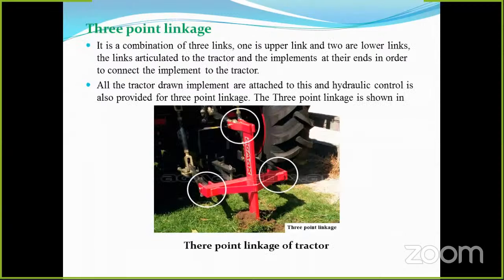Next, the 3-point hitch linkage system. See here, these two are lower links and this is the top link. By utilizing hydraulic power, the implement will move in the downward direction, and its own weight also causes it to move downward.